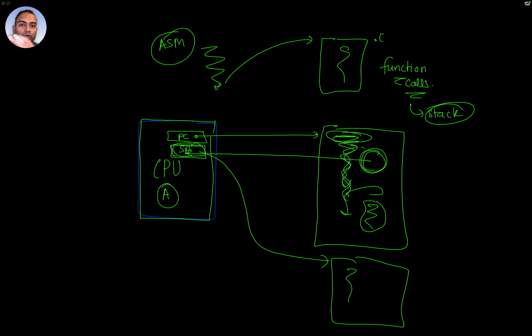The program counter is going to point to a memory location and start to execute from there. But if you have your code that is a result of the C language and function calls are involved, then you must also set the stack pointer. And this is key because, as we explore in our case study, we'll take a look at the fact that the stack pointer was loaded. This is now single core boot.